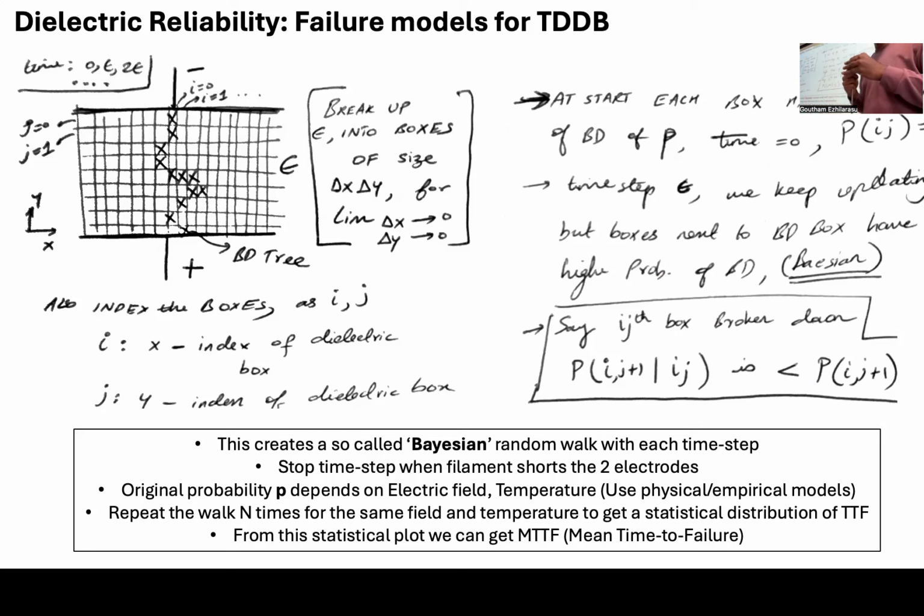No. As it breaks down, it does affect the behavior of the dielectric, yes. Of course, because you're replacing a certain region with air, essentially, as you break down. Imagine you're doing this game, and it broke down here, and then the next one here, next one here, next one here. Then this region is essentially behaving like air, and slowly over time your dielectric is failing. It's becoming worse and worse, and eventually it shorts out.